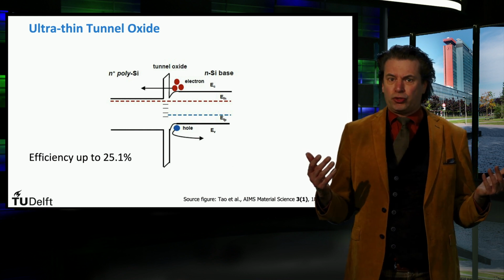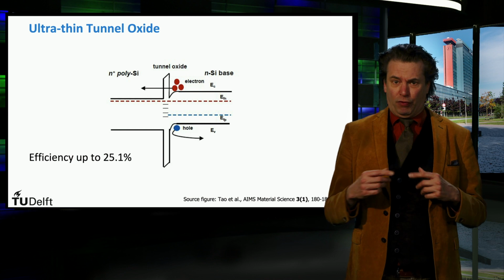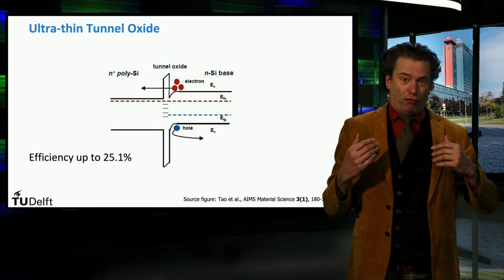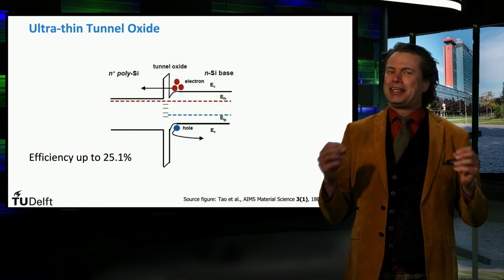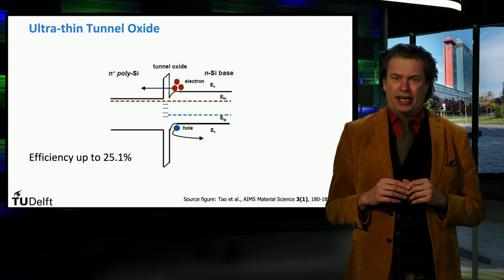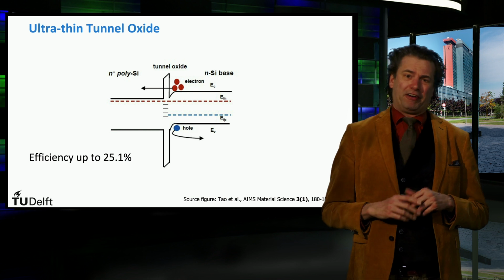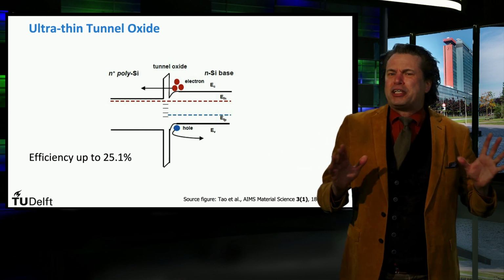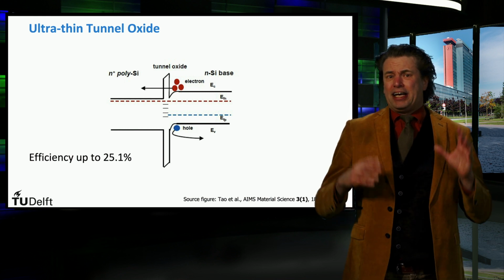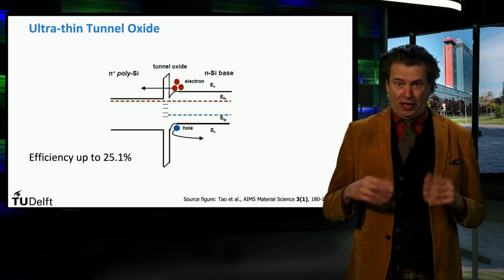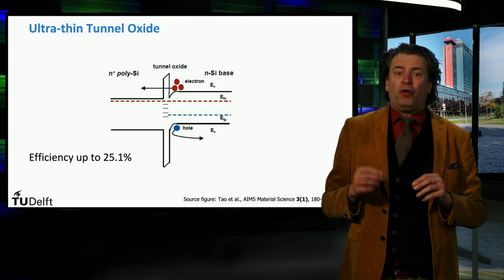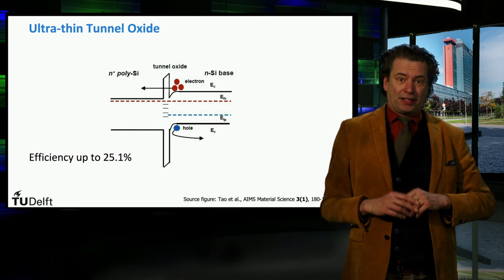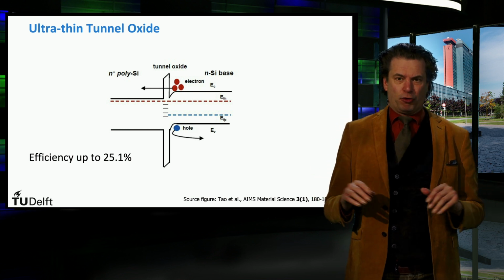In contrast to classical mechanics, in which a particle cannot move through such a barrier, in quantum mechanics this is still possible, since this oxide layer is kept very, very thin. A large fraction of the electrons can move through this barrier, and this phenomenon is called tunneling. Therefore, electrons are able to tunnel through the barrier and be collected at the back contact with virtually zero loss.